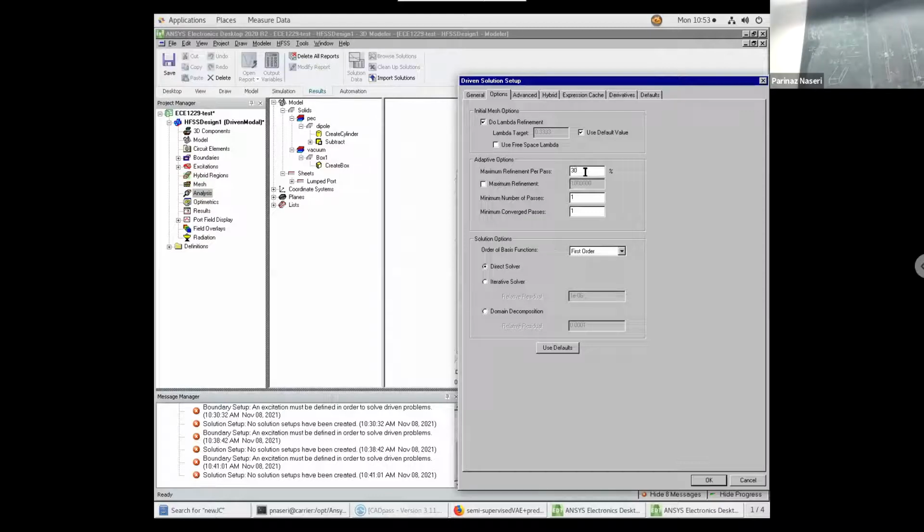In pass number 1, we might say, okay, I'll just consider 2 triangles. I would divide this square into 2 mesh cells, 2 triangles. Pass number 1 solves it. It sees, oh, things are not good, actually. Or actually, pass number 1 has no delta, so it just solves it and goes to pass number 2. In pass number 2, depending on this 30% or 40% or whatever number you indicate, it tries to go to, I don't know, 4 triangles like this.